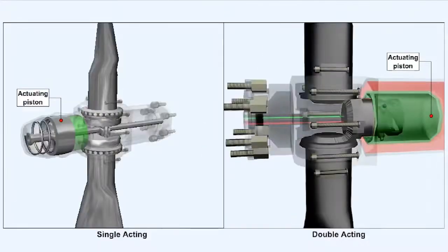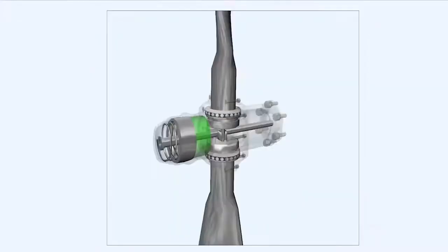Hydraulic pitch change mechanisms can be one of two types, single-acting or double-acting. A single-acting propeller has oil pressure applied to only one side of the piston. The return movement of the piston requires the force of a spring, or sometimes compressed gas.